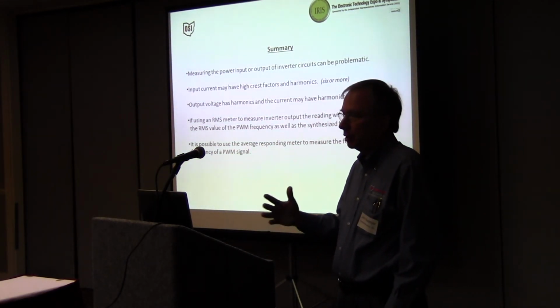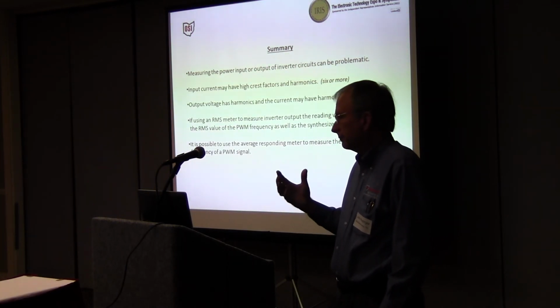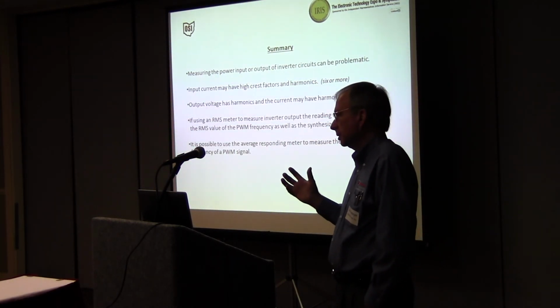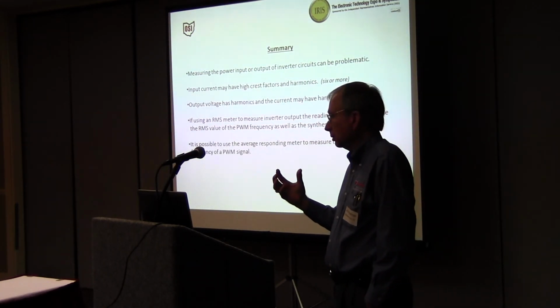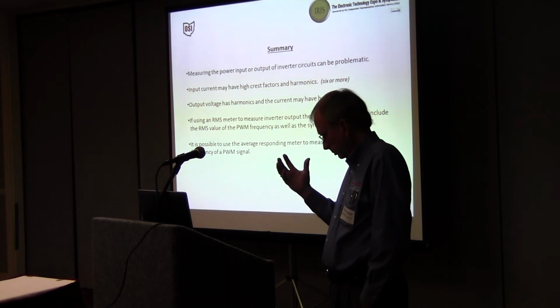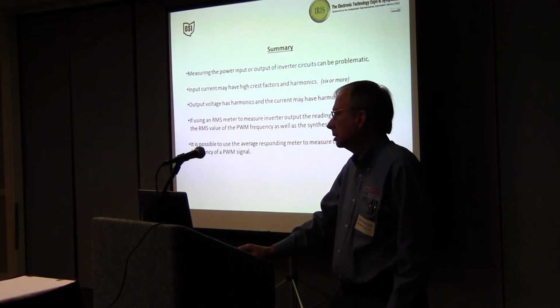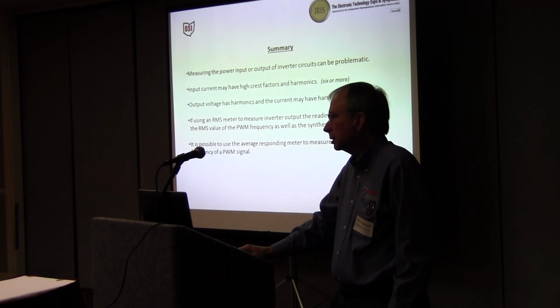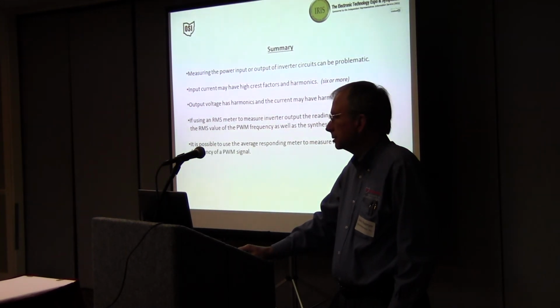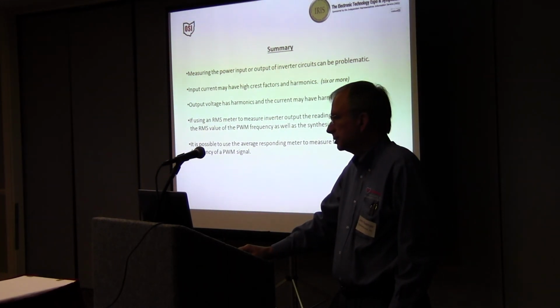So from an equipment manufacturer's view, if you're using a current transformer as an input sensor for your watt meter, now you have to start worrying about the efficiency of it. Is it even going to work at 2 hertz? And then on the high end, 400 hertz. So soft starting can be an issue to the measuring device, because the frequencies vary so much.